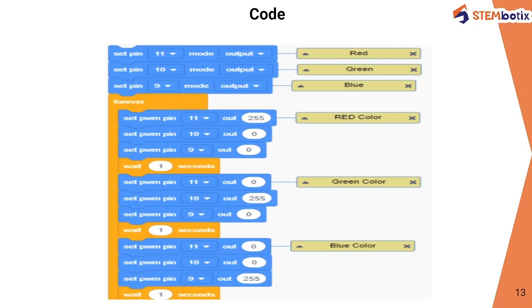This is the same principle behind film and television, where a rapidly changing image tricks your brain into seeing continuous motion. By turning our LED on and off repeatedly, we can trick the brain into seeing an average brightness value based on the duty cycle of the driving PWM signal.